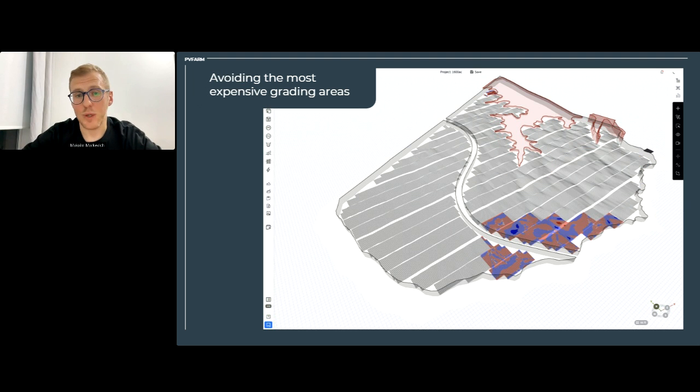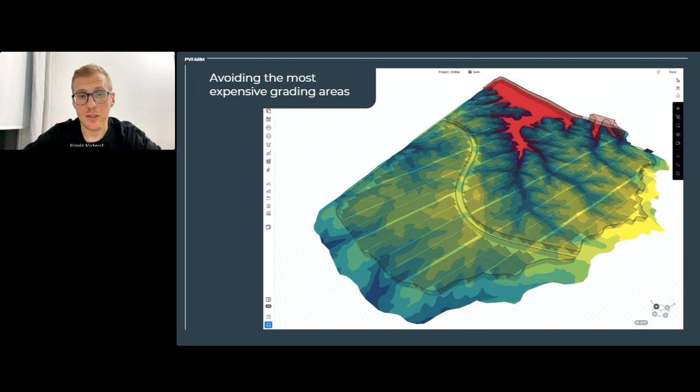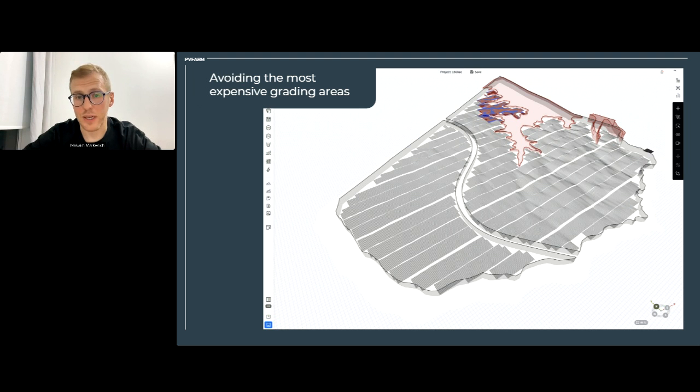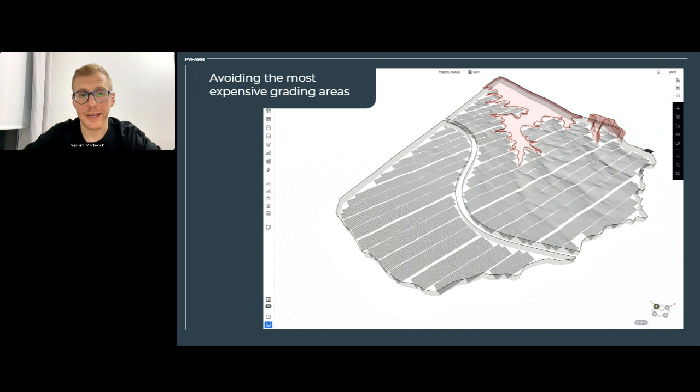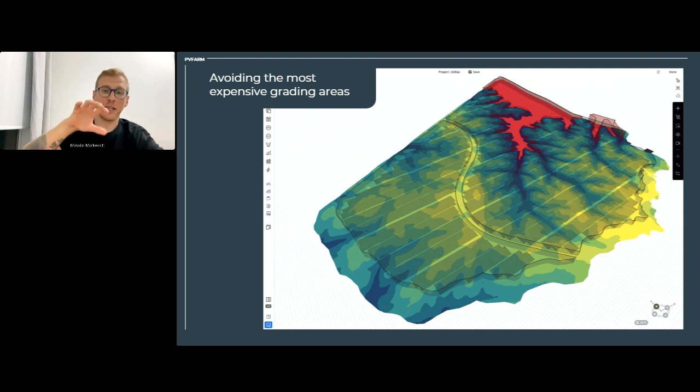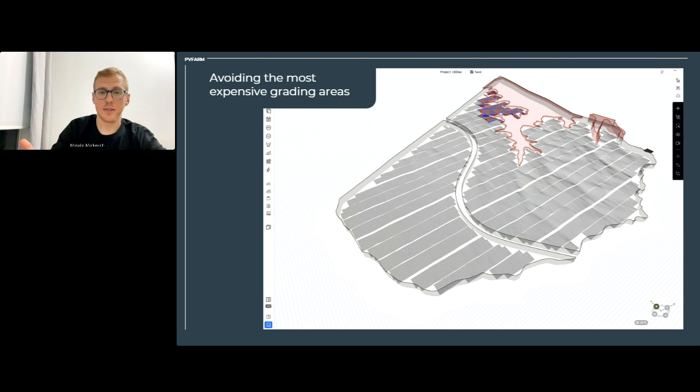So what we recommend in PVFARM is running a bunch of chunks of places. You place trackers, select different chunks, and run the simulation. You run the gradient strategy, and you understand the cut fill implications. Because we have an adaptive cost model that works at runtime, you can get dollar per watt. Then you have a bunch of spots with different dollar per watt, so you can understand quite scientifically what the worst place is.